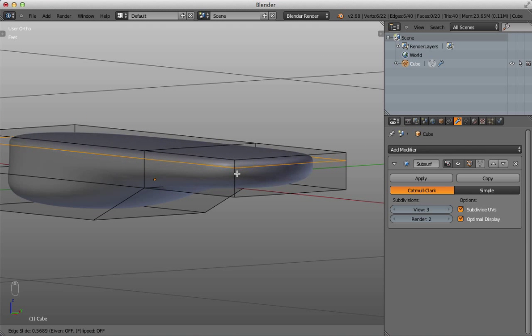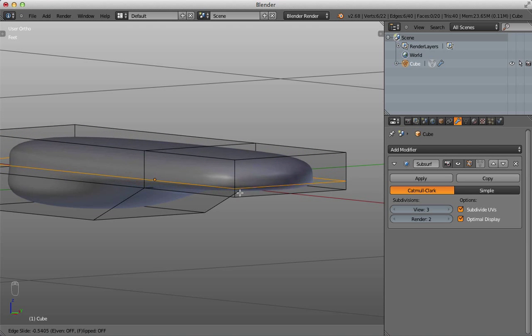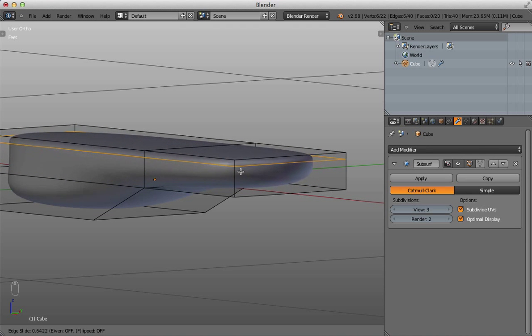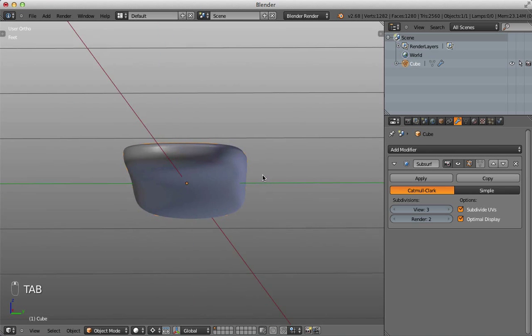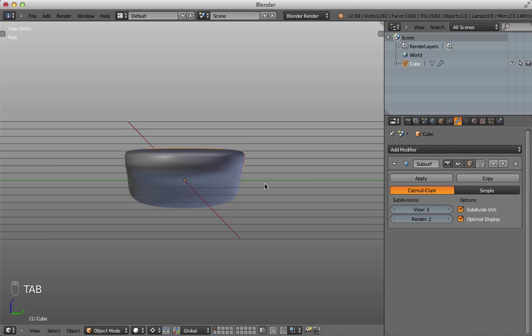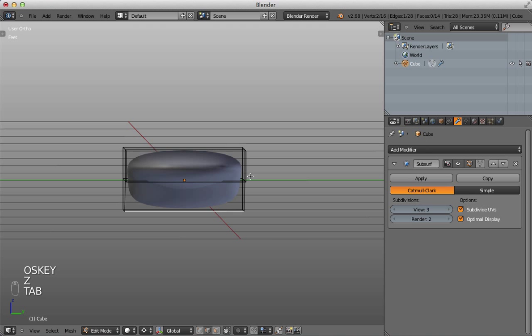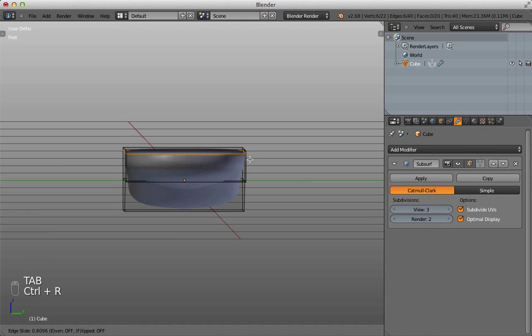Click on a vertical edge and then move my loop cut up and down. You can see once you add the loop cut, you can slide it. So this is called edge slide. And maybe I go to there. Don't go right next to it, a little bit below. And you can see that this command actually, I undo it, starts tightening the surface.